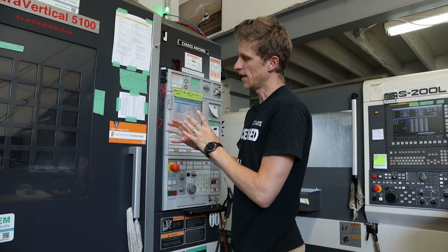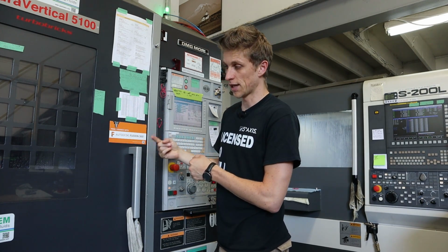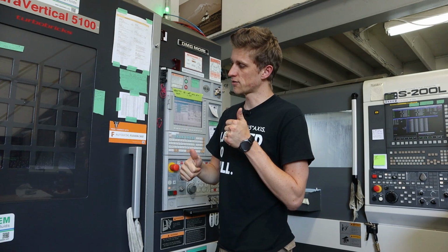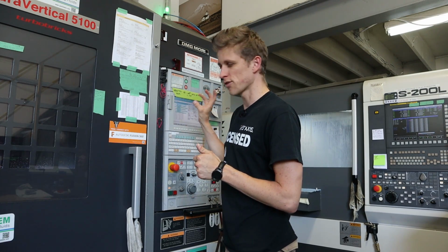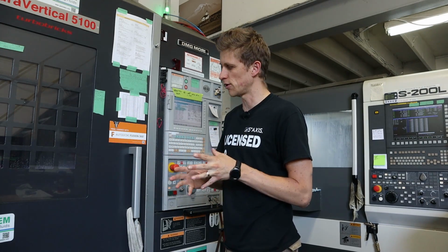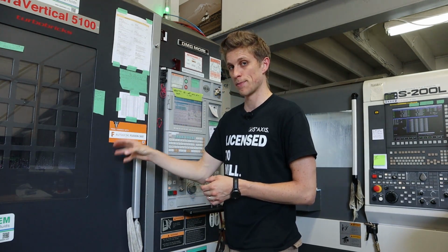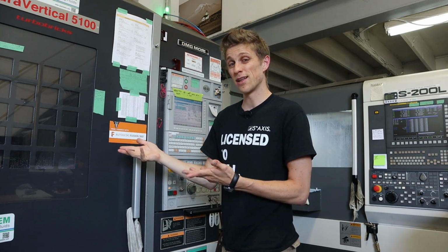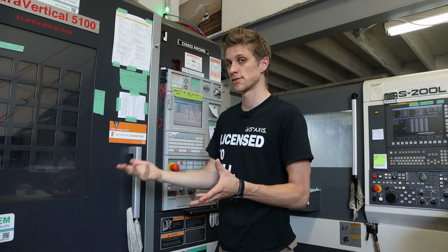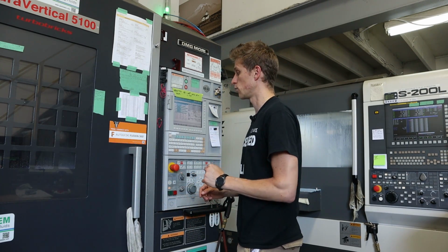So, in order to monitor the tool life on every single end mill, we've got 30 tools in this machine. I've been trying to figure out ways to monitor the tool life. There's a way on the machine that monitors by minutes or hours or whatever, but I don't like it for various reasons. Since we machine basically repeat production of our Norseman pallets, I want to know how many pallets a tool can last for. For the 1/4 inch 5 flute rougher, I want to know how many pallets that lasts, and when to replace it early so that I don't run into a problem with a late worn out tool.